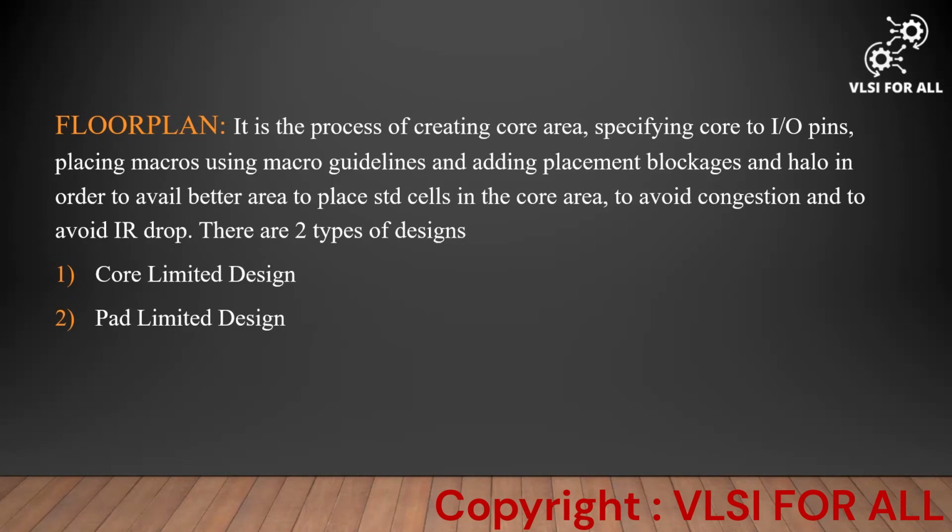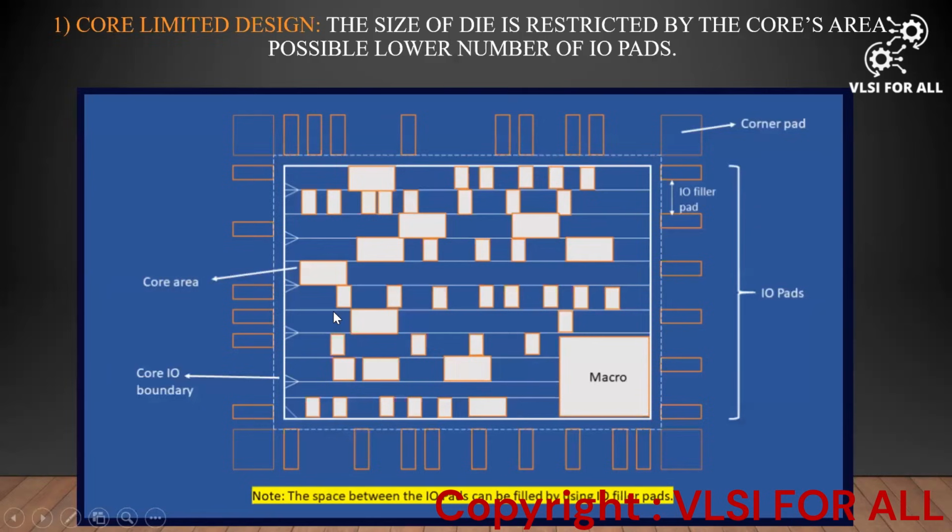We'll place the macros, and after that, if any additional placement blockages are required, we'll place all those blockages in the core area, which is the basic start of the PNR flow. In floor plan, we have two types of designs: one is core limited and another is pad limited.